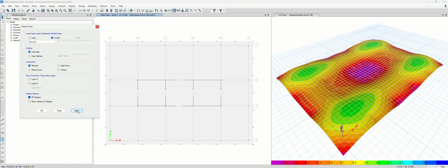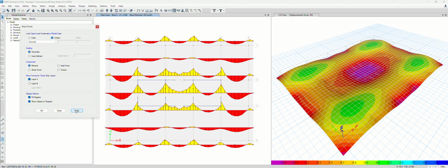Similar to shear force, let's check the moment in the Y direction. If you want to turn on the values on the diagram, turn it on. So maybe you can just show this diagram in your report or PowerPoint, and follow along each procedure one by one and verify, so that you can learn instead of just jumping right away to design. This is validation again. When you create your model, you should check one step at a time and make sure everything looks reasonable. If you want to check something with dead load plus wind effect, you could see this, right?